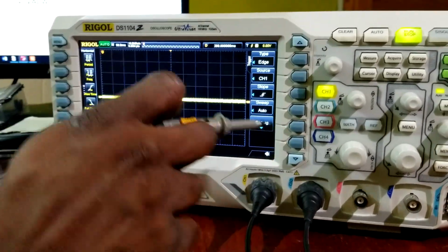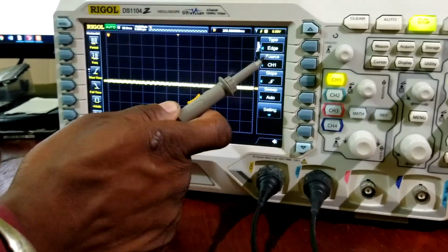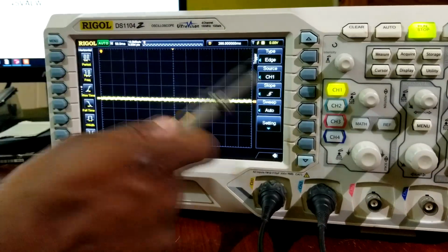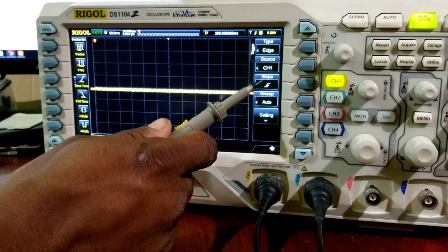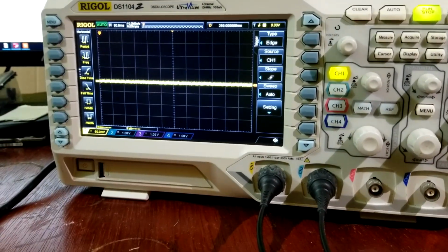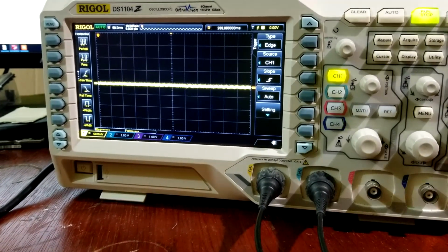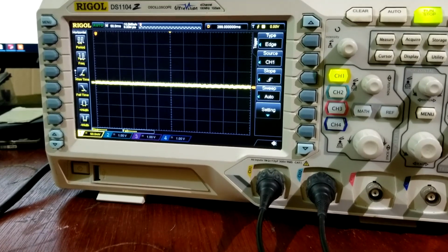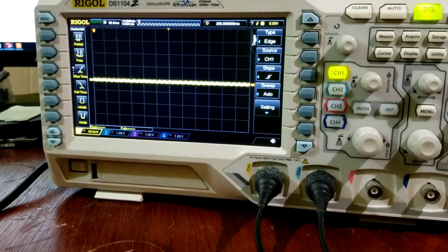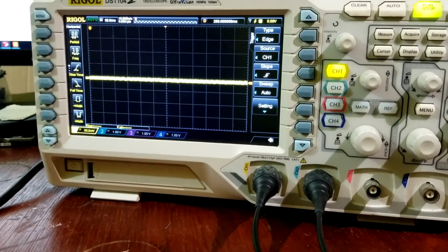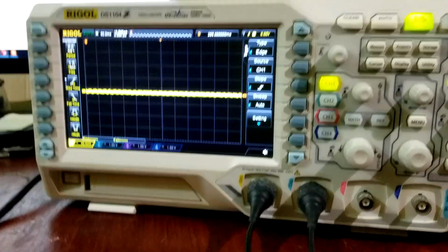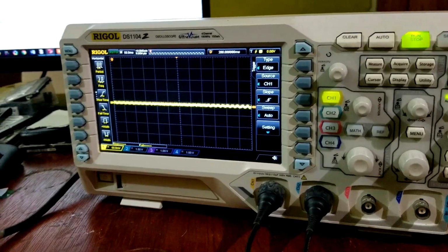Very important. The first thing when you're setting your trigger settings, your type must be set to edge, right? Our source is channel 1 because we're using 1 probe. Our slope, because we're measuring a falling edge. Remember, when the BIOS is being read, it goes from high, 3 volts, so you need a falling edge, not a rising edge, because the BIOS basically reads chip select and the signal falls, so it chops the 3 volt signal into several pieces, right?